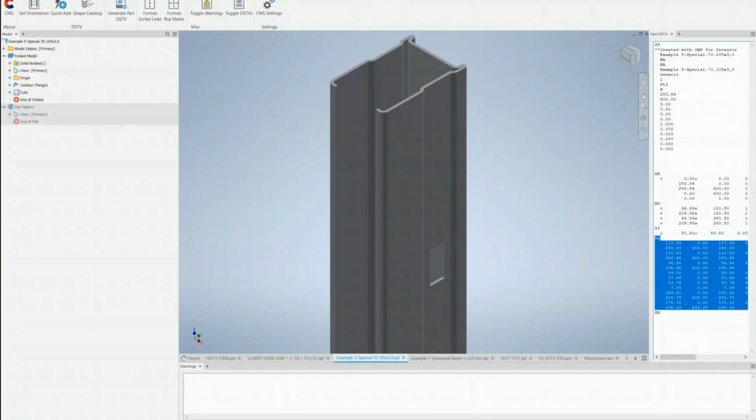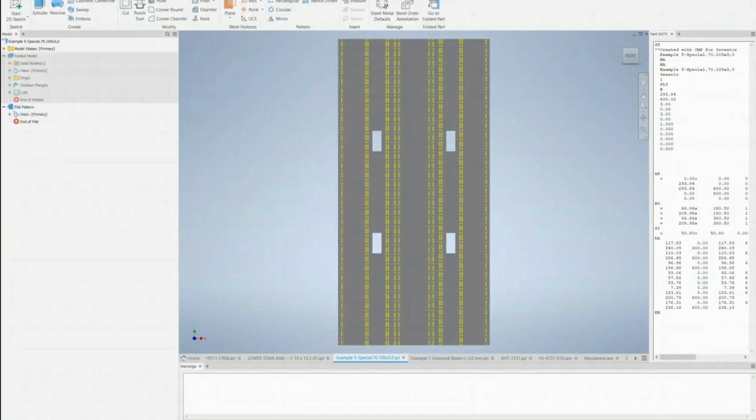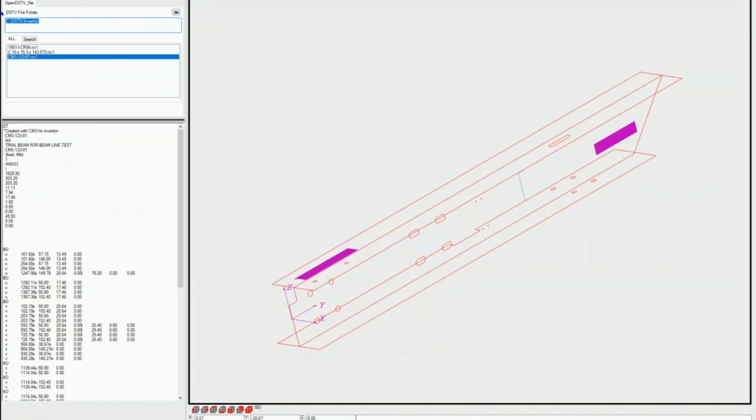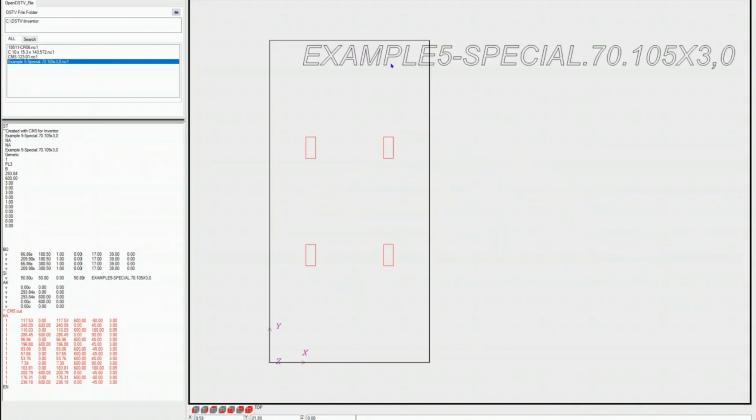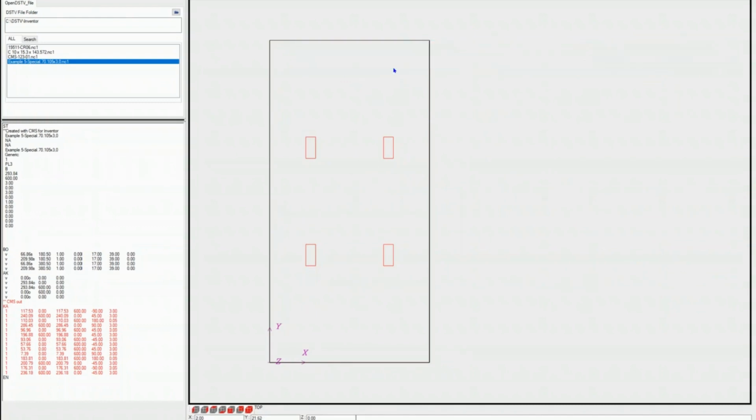K stands for your bending lines, right? So remember those bending lines. It actually gives the coordinates of those bending lines, the rotation angles and the radius of the bending as well. Okay. So if I try to see that in my NC1 viewer, which is the CMS viewer, it will not show me the bent part. This is the big line showing up over here because it's coming from my default stamping. If I don't want that, you can hover over it and press delete, and it is going to be gone. And those lines, as I mentioned from the very beginning, are your marking, so your bending operations. If your machine can handle that, then you can do the bending from here as well.